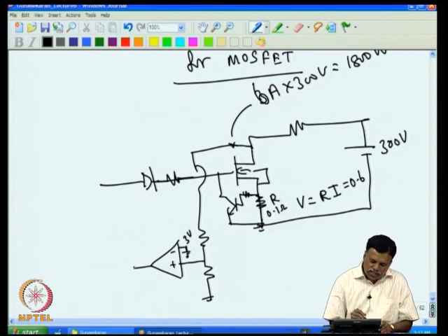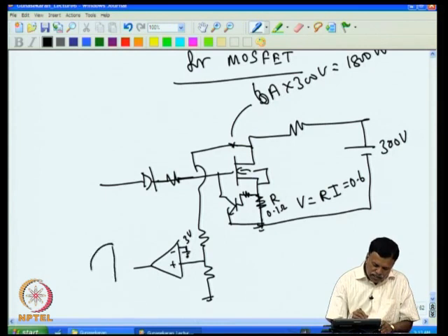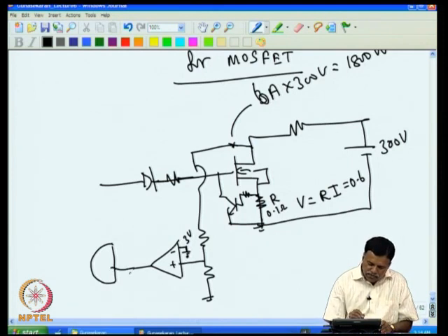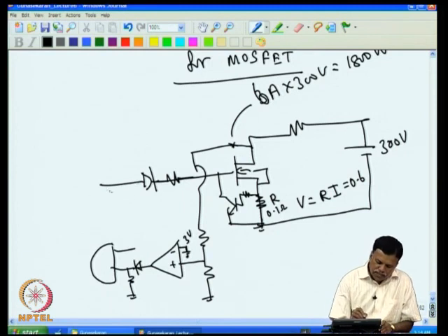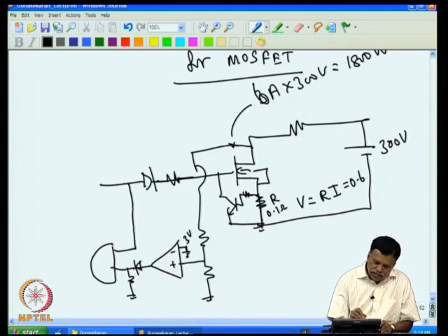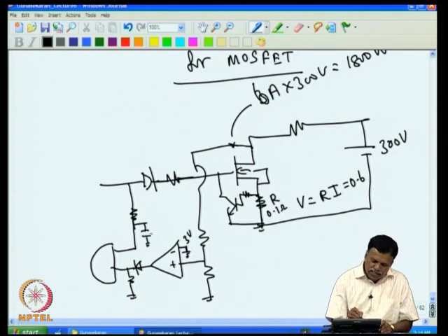Now what I do is, this high voltage should pull down, but that should pull down only when the gate is on. So I do one more trick at this point. For example, I can have one gate here, say a CMOS gate, and I apply only the plus here. Then I have another input that I apply from the output of the pulse here. If this is high, then I put one small divider here, an RC network.